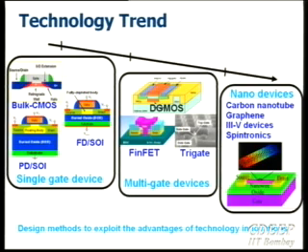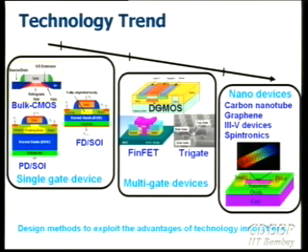These are certainly technologies that have worked really well, and people are possibly going all the way down to 22 nanometers even with these kinds of technologies. But from the scaling point of view, having a better aspect ratio of the device, which is basically the lateral dimension to the vertical dimension of the device, it turns out that devices with gate all around, or gates on the two sides of the channel, or tri-gates, as an example, are turning out to be quite important. There's been a bunch of research work done in the area of FinFETs, tri-gates, and so on. However, the probability of that happening down to 15 nanometers or 20 nanometers is there.